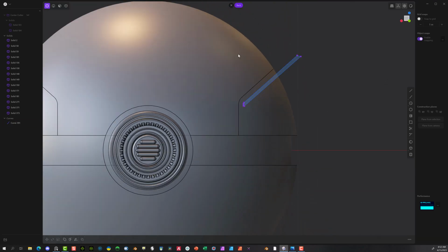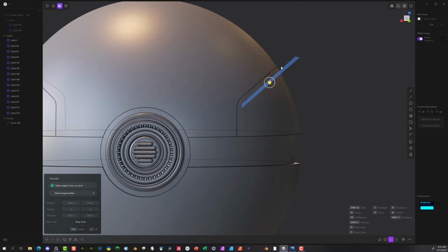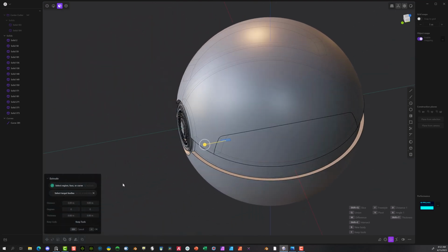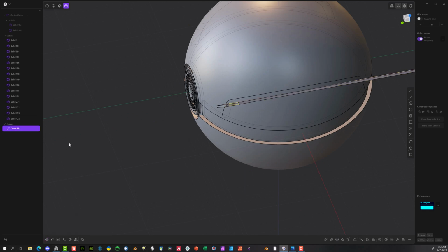And we can actually select that now. Just go ahead and go to Face Tool. We're going to go ahead and select this. And one thing I could do is either cut it or just extrude it. So I'm going to hit the E key. Go ahead and extrude all the way through. Say OK. Just bring it back through. Get rid of this curve. All right, one thing you can do is do that.